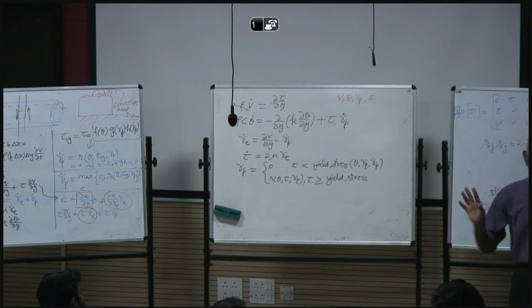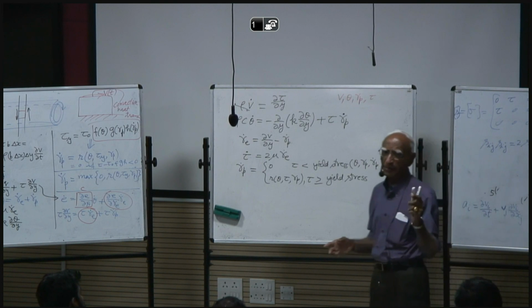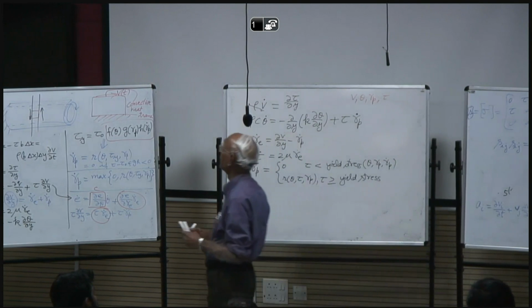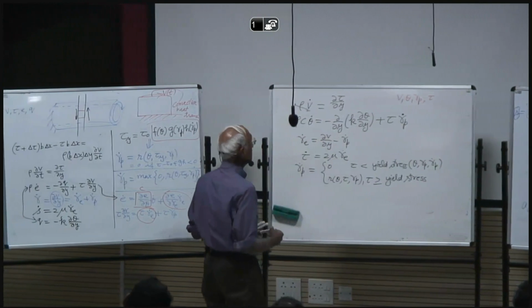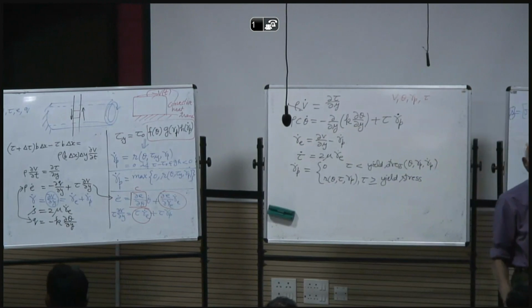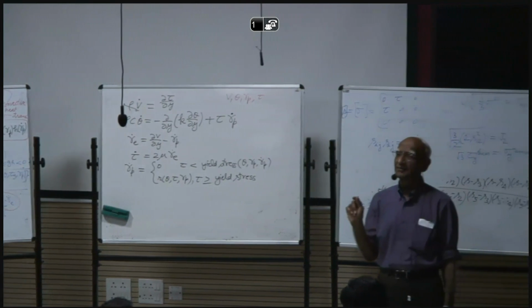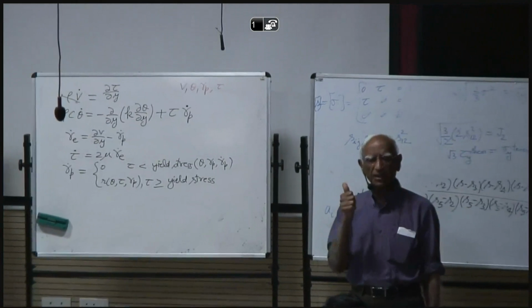If you apply a strain rate of say 1000 per second, which is very typical, this is nothing. Locally the strain rate can be a million per second, wherever the defect is. So locally the strain rate can be very high, and that's where the failure will occur. All you need is one inhomogeneity in the body.